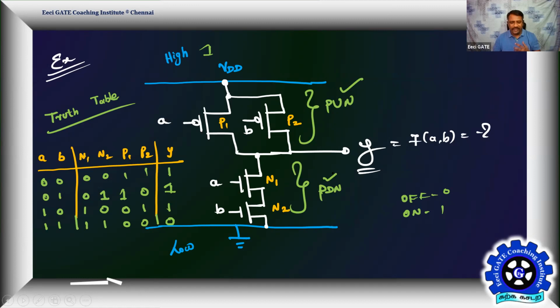So how to design such a thing? The moment you put NMOS switches in series, by default, the rule of thumb is that the PMOS switches have to be connected in parallel. Or if you put PMOS switches in parallel, your NMOS switches must be connected in series. The two PMOS switches sensing A and B are connected in parallel, which means automatically the NMOS switches forming the pull-down network should be connected in series. That's the logic we need to follow.